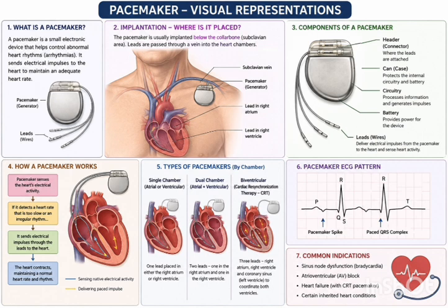The main components of a pacemaker are the battery, which is lithium iodine, pulse generator, control circuit, LEDs, and finally the titanium casing. In working, it first detects the heart's electrical activity and compares it with the programmed heart rate. If the heart rate is too low, it generates an electrical pulse. The pulse travels through the leads to the heart, and the heart contracts and maintains normal rhythm.